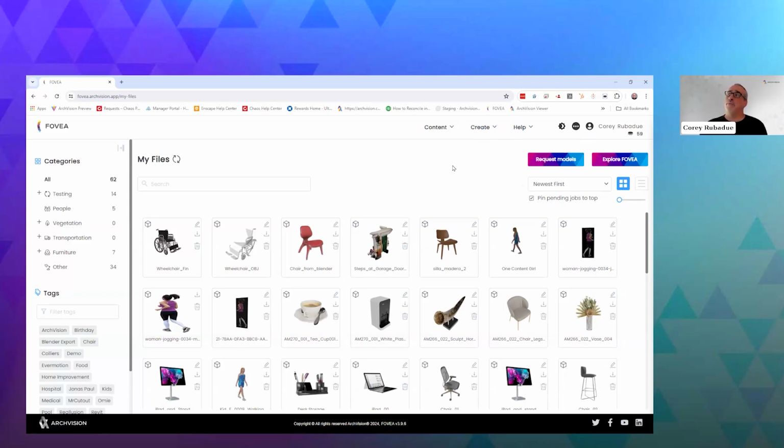When models get published, we add metadata to the published assets, and that metadata is critical for the lifespan of the assets. That data travels virtually everywhere that data can be supported. We try our best to get data into SketchUp and Rhino, for instance, but where Revit handles data for objects and elements, the metadata layer that we have on top of our assets for categories is honored and supported inside of Revit.